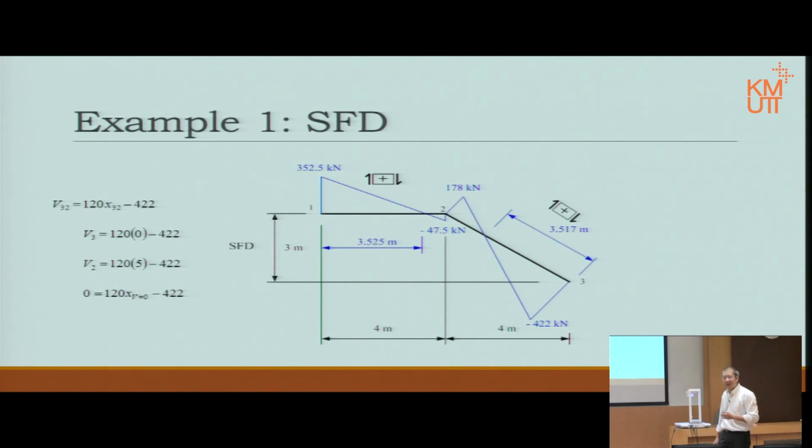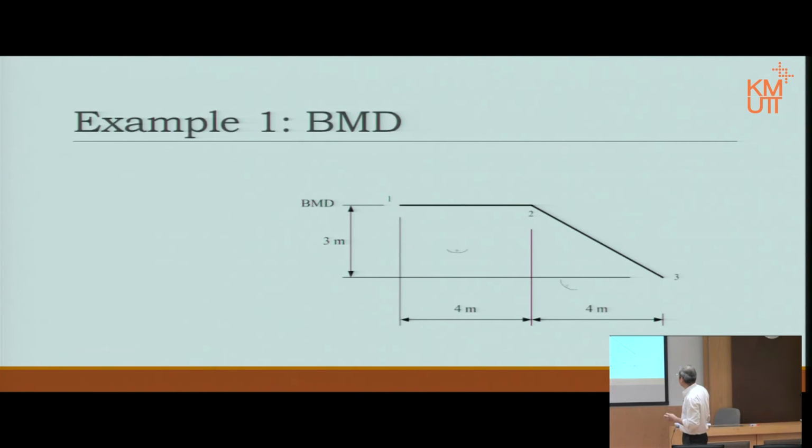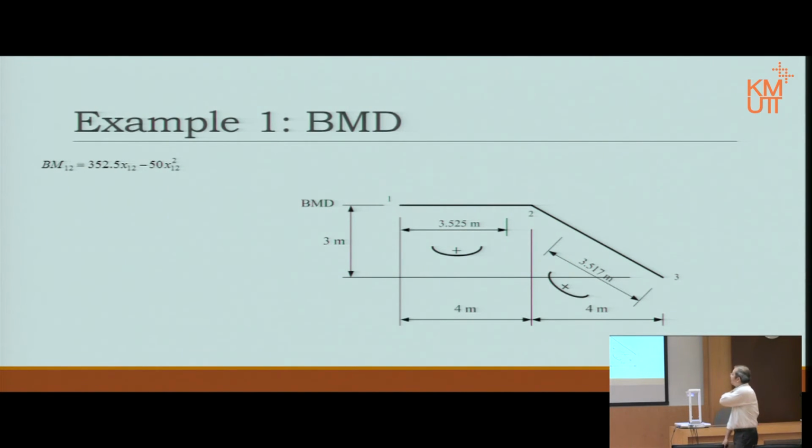Now again, I emphasized already, the bending moment in both cases will peak where shear is 0. So we mark where 0 is on the bending moment diagram, give the direction of the positive side. That is where the bending moment must peak, because we already found it when we did the shear force diagram. Between 1 and 2, that is the expression.